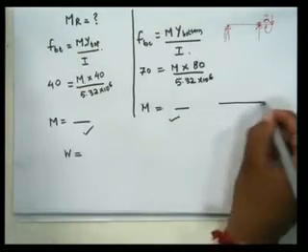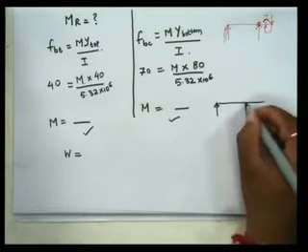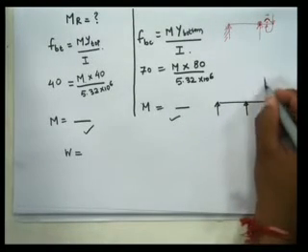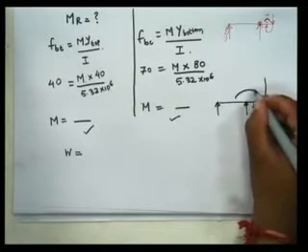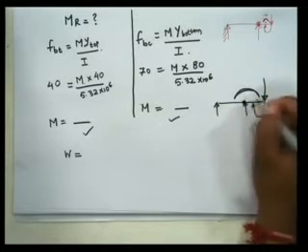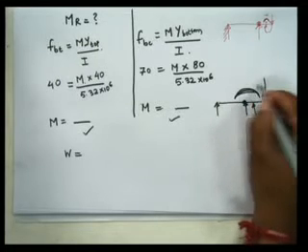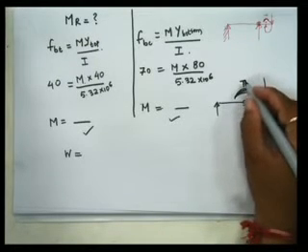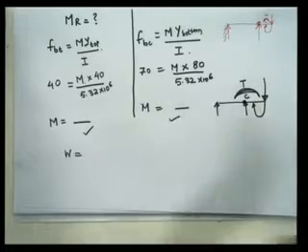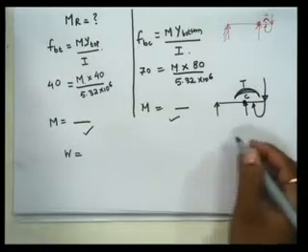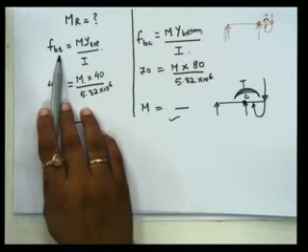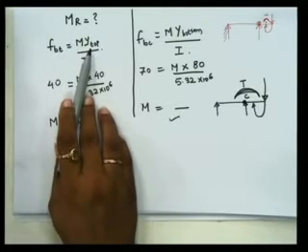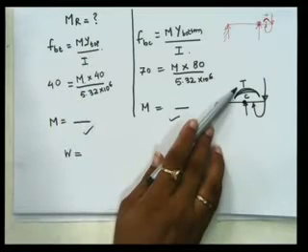Again I'll explain. See, this is like this. I'll draw a big diagram so that you are able to see. Now when the load is converted in terms of a moment, it will rotate like this, and at this particular point, it will be a which moment? Hogging moment. So on the outer side, top is tension and bottom is compression. That is why, if you see, what I have taken is FBT. FBT is what? Tension. So what I have taken? Y at top, because tension is at top. Is it clear? Why I have taken that?